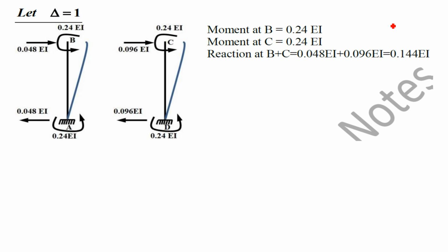Now since we are assuming sway is towards right, we have given displacement towards right, that is the positive direction. So in both the figures, sway is given towards right, positive. Now, what is the moment required to give the sway or horizontal displacement? Like the previous beam problem, where the beam member was horizontal so displacement was vertical, perpendicular to the member. Now here columns are vertical, so displacement is horizontal.